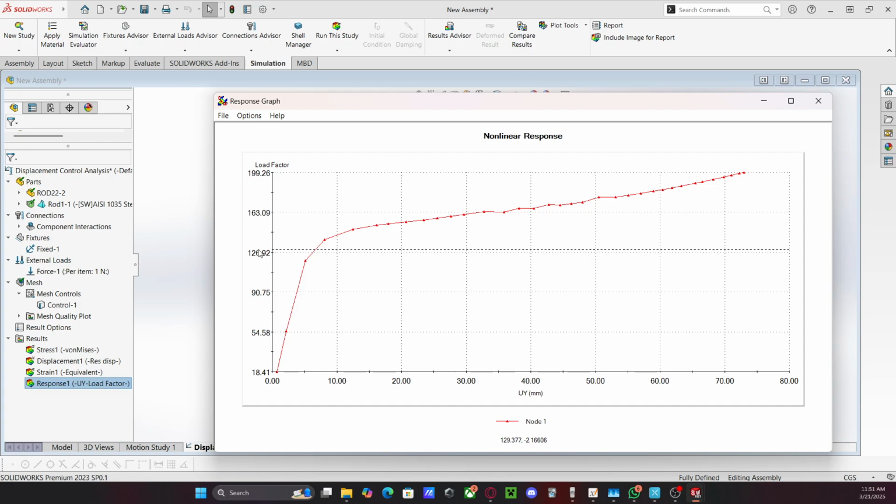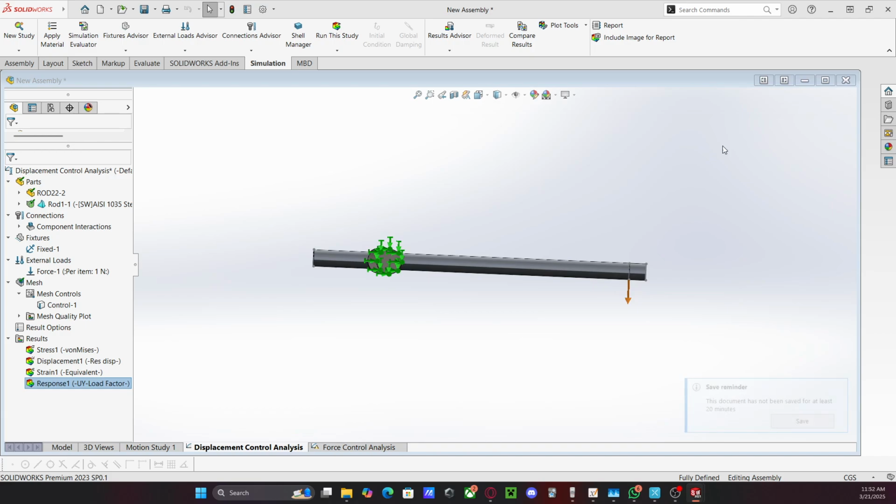And you'll notice the graph, it changes rapidly after this point here. So for example, if I put a value 150, and scroll down, you'll get a graph like this, and that just shows that it basically yields around here, and then it changes its response and becomes like this. This is the material itself. Now you can do the same analysis for changing for steel and for aluminium. Okay. So let's just save this before we forget.